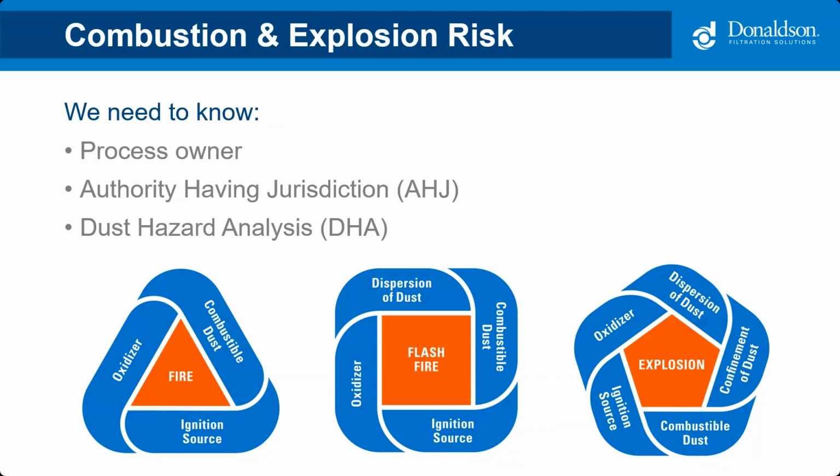We actually have a whole other webinar on combustible dust that you can watch on our website. For now, it's important to know that laser cutting fume may be combustible and explosive, and it's an important design consideration. We typically need to know things like who the process owner is, who the AHJ is, and then information such as KST values from the DHA to help customers make informed decisions on the best mitigation systems.